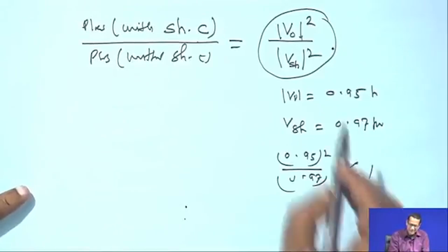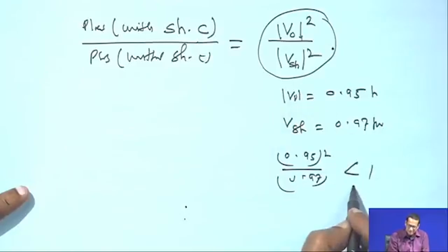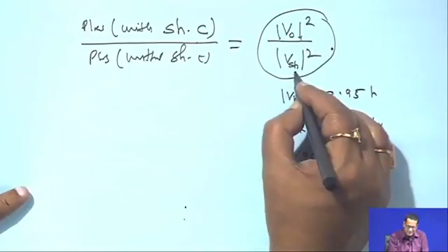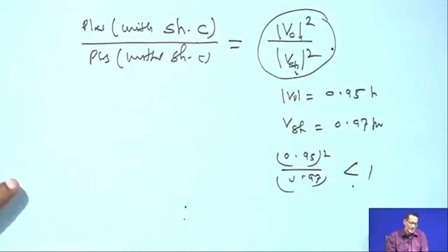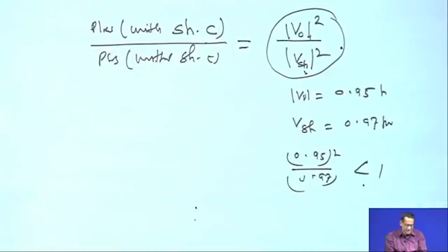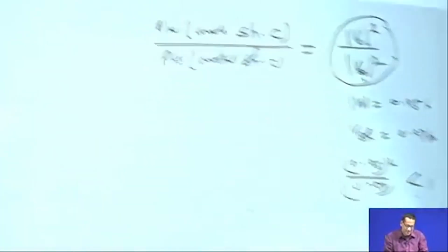But otherwise the shunt capacitor also improves the voltage level. So, it also reduces the losses, but not like a series capacitor, because in the series capacitor case the voltage rise is very high. So, these are some general ideas for series and shunt capacitors.